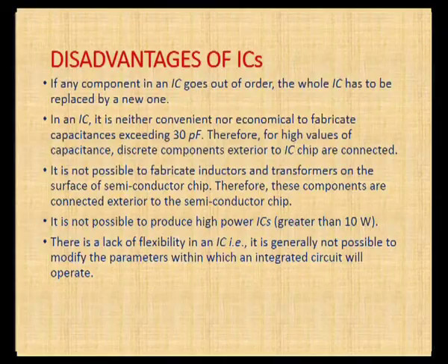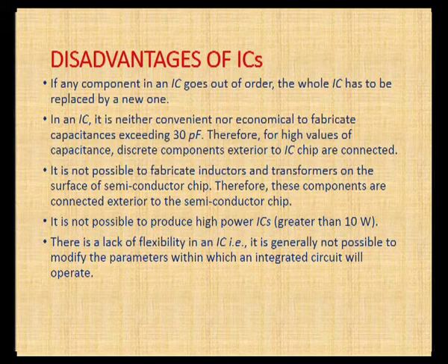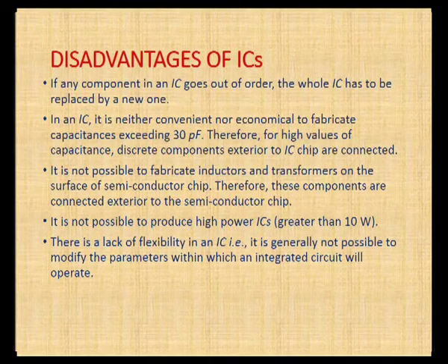Also, in ICs we can't fabricate an inductor or transformer. Therefore, these components are also connected exterior to the ICs. And one more thing, ICs cannot work with high power, that is greater than 10 watt. The circuit is not suitable for that.